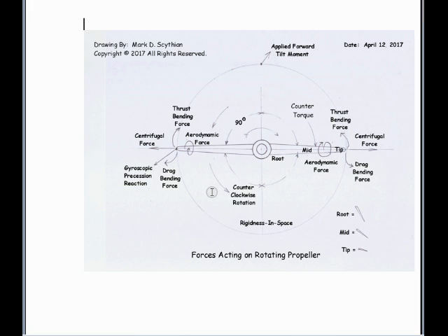And so therefore, let's say this is the front of an airplane that has counter-rotating propellers. So let's say this is the right propeller looking at the plane, and we have another one just like this, a left propeller. So the right propeller is rotating counterclockwise, the left propeller is rotating clockwise. So now, because the right propeller is rotating counterclockwise, let's say the pilot climbs by positive pitch rotation. The right propeller is going to have a precession moment tilting it to the right, causing a right yaw. If the climb is positive angle, it's going to tip or cause a moment to tip the right propeller forward, causing a right yaw. But the other propeller is rotating clockwise, equal and opposite RPM, and causing a left moment.